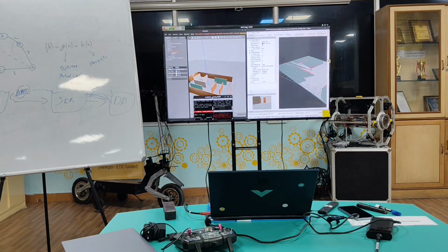In Fusion 360, I have heard of it, but I have never worked with Fusion 360. But there are multiple options, right? While exporting a Fusion 360 file, there is an option called URDF. If you click that URDF, you will get the basic URDF of your system itself, and you just have to include your sensors' XML code into your URDF file, and if you deploy it, it will actually run. I can explain the deploying steps, but it will take more time. That's why. Okay.